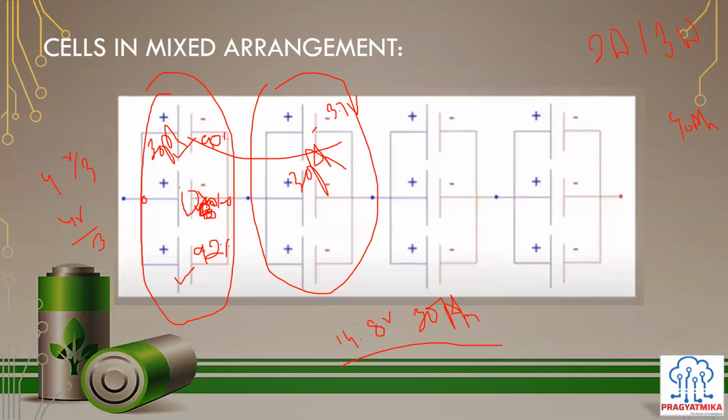So what will happen in this case? Once the balancing algorithm runs, if it is passive balancing we are doing, it will observe the total capacity of the battery pack by adding the current or the capacity of all of the cells, and at this module level, the capacity would be lower compared to the other one. Because the capacity or the current, if it is getting discharged, at this module level we have the lower values. If all of them are getting charged up to 90% SOC or the capacity related to that, but because these cells are connected in parallel, the total effect will be lower in this case.